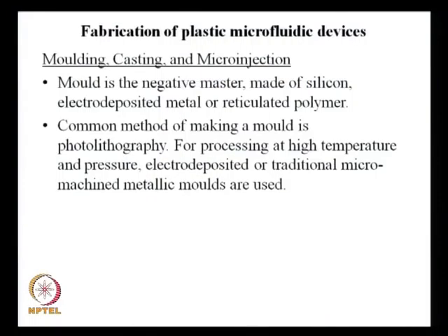I welcome you all to this course on microscale transport process, to this lecture of microscale transport process. We have been discussing plastic microfluidic devices. We started with microfluidic devices, the manufacturing of microstructure devices, and what we have considered so far is silicon and glass, and we have discussed various techniques to etch a channel on that substrate and how to bond another silicon or glass structure, glass wafer on top, so that a watertight microstructured device can be fabricated. These we have already discussed.